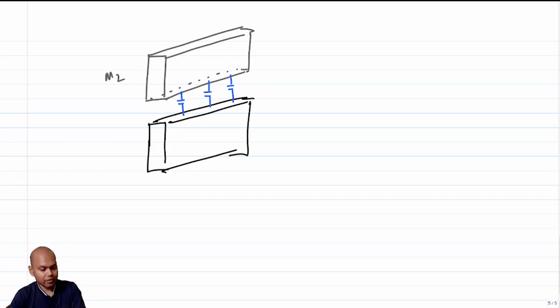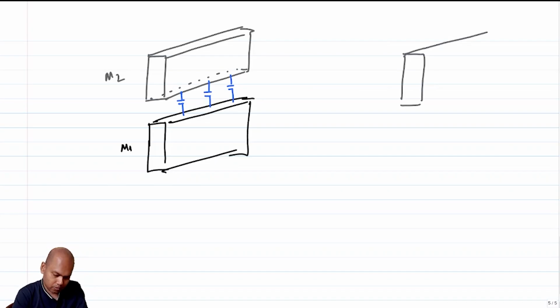This might be an exaggerated picture, but the reason I showed you this picture is that something should click in your mind that there should be another way of realizing a capacitor, and that might be two metal two lines. Say I have one line here and maybe another metal two line placed nearby.